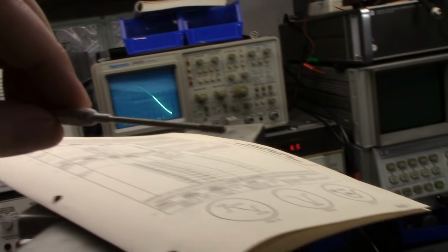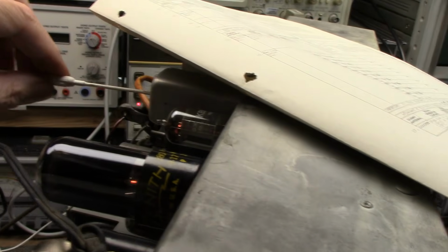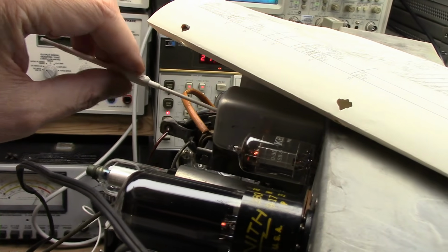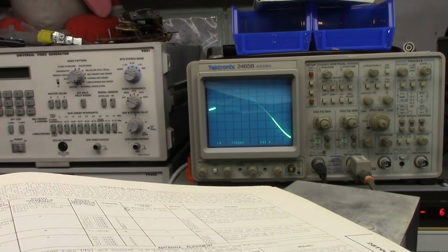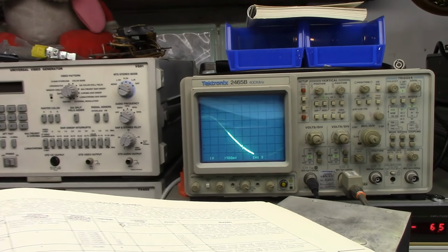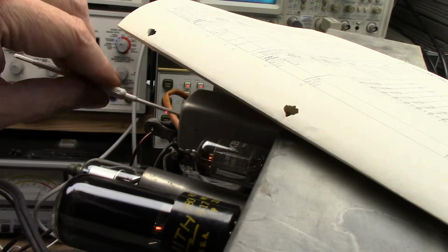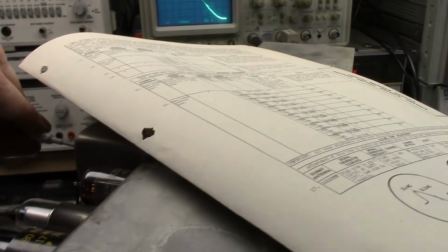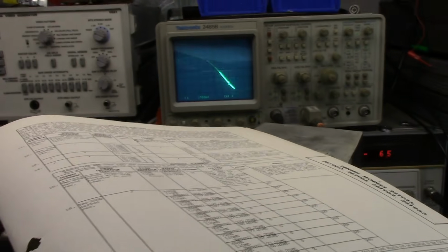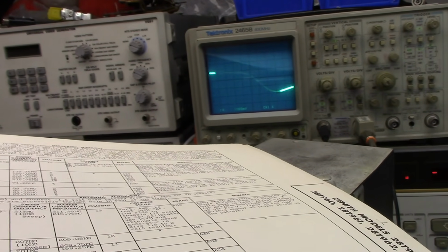This is the kind of tool we need. Plastic with hexagonal shape on the end. We go into the top, carefully feel around and get the top slug, and adjust that. Boy, that certainly has a very distinct effect on the waveform. Let's get that about there. Now if I continue to insert it, feel around, there's the bottom slug. Okay, adjusting that also affects things.